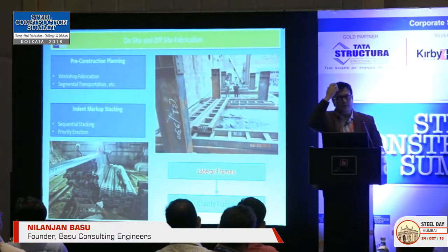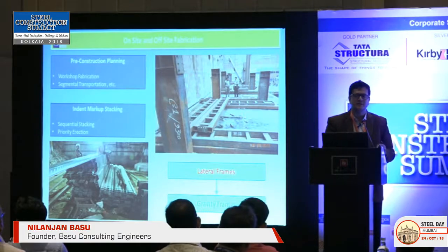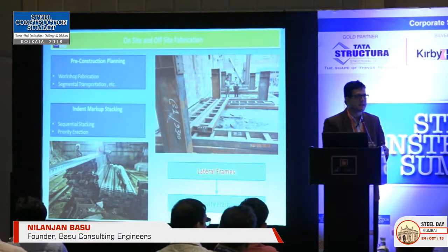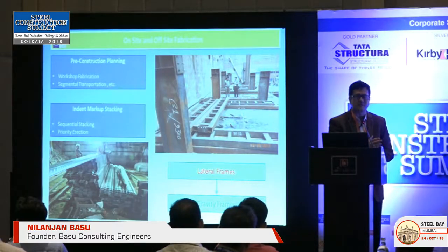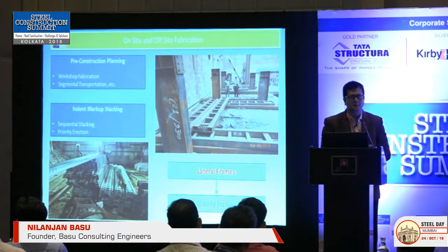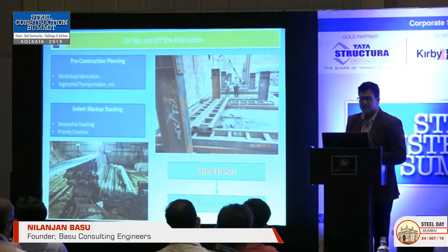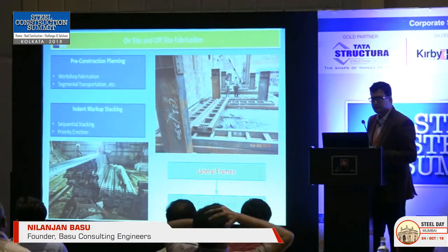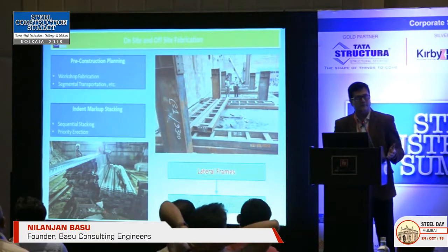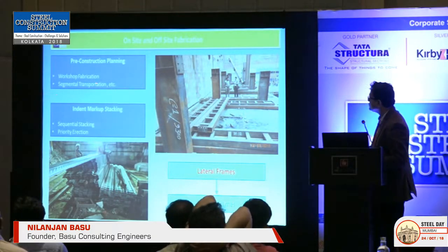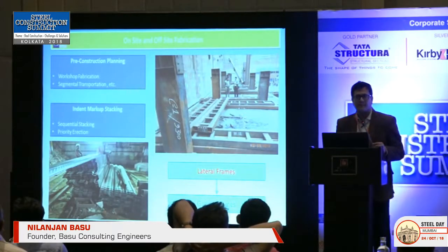Okay, so when you get the deck, you have to stack it according to your constructional sequence. You can't just stack it as per your requirement. If you do it as per the constructional sequence, you are stopping the waste of time for any of your construction. So in the pre-construction planning stage, along with the contractor, and we involve the architect also, we do some workshop fabrication planning.